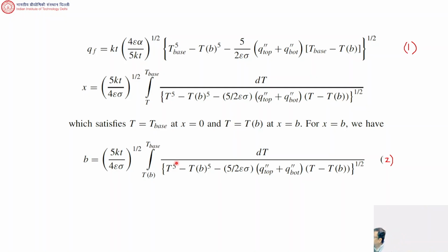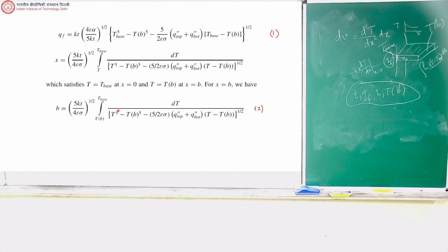You get temperature to the power 4 because the Stefan-Boltzmann law says that Q comes from Planck's law. After you do some integration, you get heat transfer as epsilon sigma area times T to the power 4 minus T surrounding to the power 4 for a simplified case. Otherwise, there will be view factors also, and you have to do a more complicated analysis. For a simple case without view factors, it's just epsilon sigma A times Ts to the power 4 minus T surrounding to the power 4.